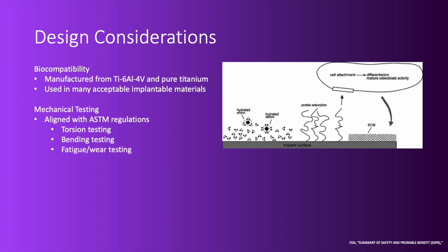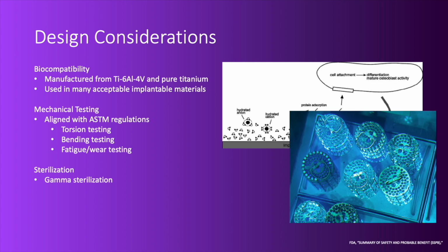Wear testing is also performed on components with variable interfaces, such as the abutment fixture and screw, to ensure that everyday usage will not result in abrasive failure. Other concerns such as sterilization and shelf life are also indicated for the OPRA system, where gamma sterilization procedures occur during manufacturing of all components, and the uninstalled implant has a shelf life of 5 years after sterilization, as sterilization procedures can result in accelerated wear or oxidation, leading to variance in the specified geometry.